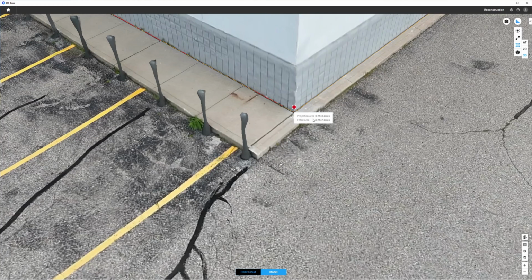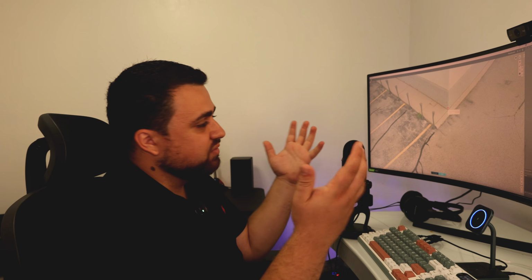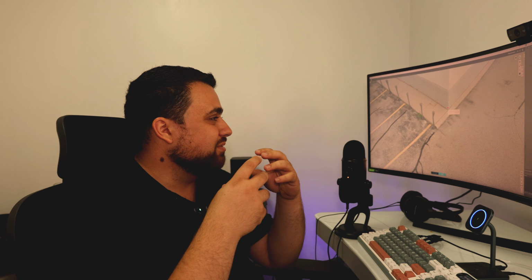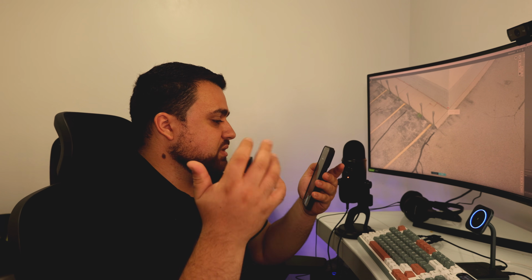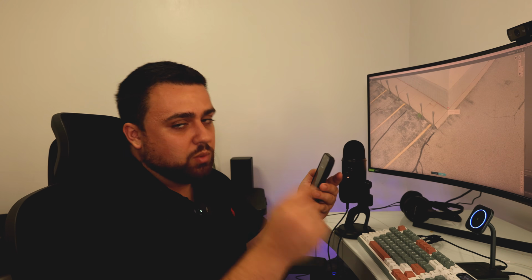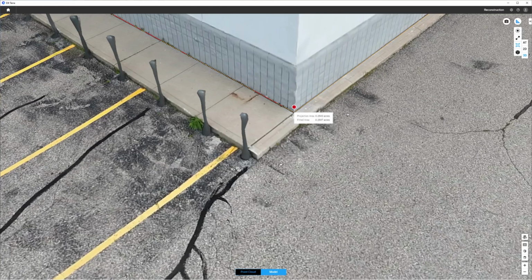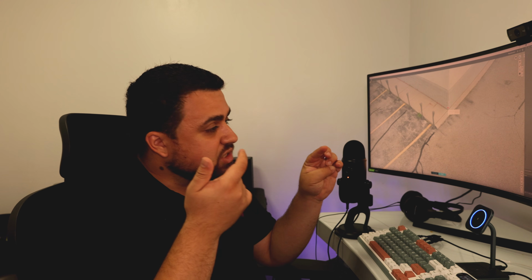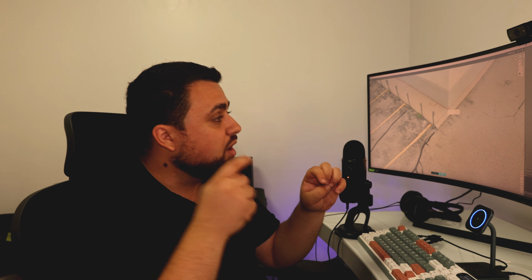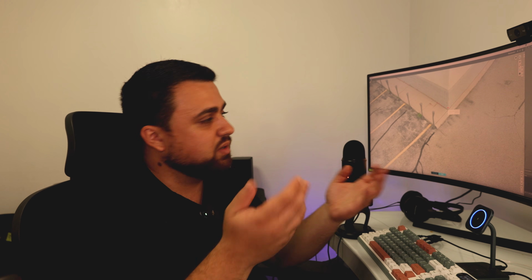All right, so we've got an area of about 0.254 acres. Of course, we know that area of a building is projected into square feet, so that's 11,064.24 square feet. Now, the projection area is the area based on the 3D model that exists. The fitted area is actually using the coordinates of the points that I selected. So it's two different methods to do the same thing, but it's good to understand how each one is calculated.